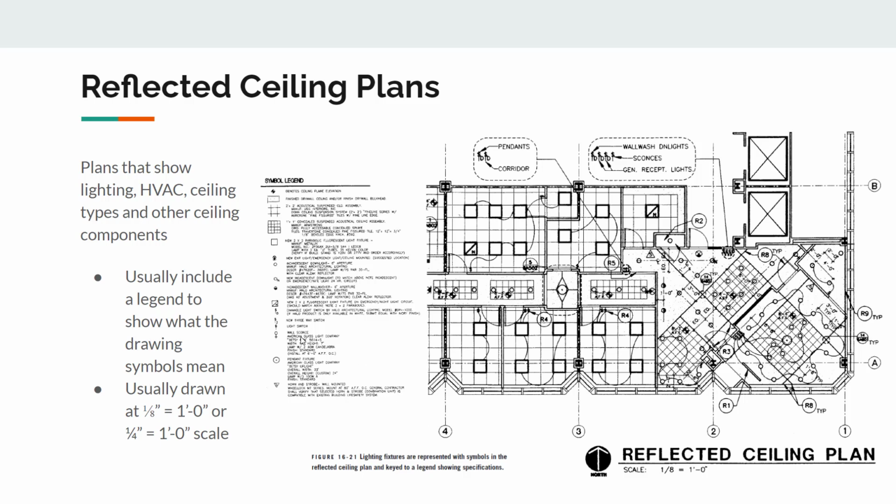And then we have other things such as wall sconces, and then we might also have sprinkler systems, things like that. These little circles over here in this part are representing can lights that are placed into the ceiling. And then these arched lines are showing the actual electrical circuit connections between all the lighting fixtures. All right. And then they terminate here on the wall, and where these terminate actually shows where the light switches are within the room.